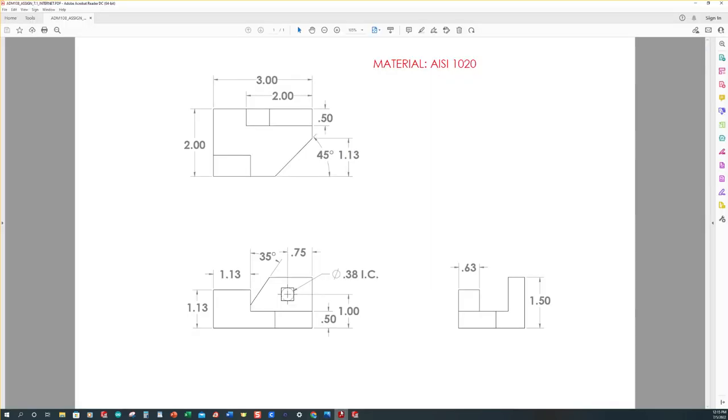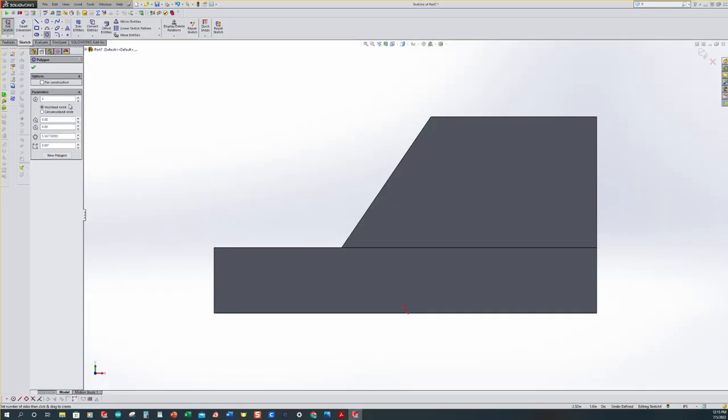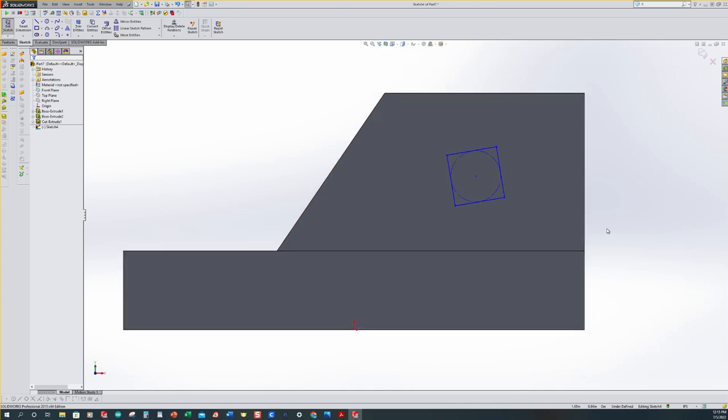If you look at our drawing that is provided, we have an inscribed circle that's touching all these lines tangent. So all of these lines have to be equal, and the way it's oriented is horizontal lines or vertical. So make sure that you put your number of sides in first. It's going to make your life quite a bit easier. So one mouse click, pull it out, and a second mouse click. I'm going to leave mine just askew, exaggerated. And then I'm going to hit my escape key a couple times so we can see what's going on.